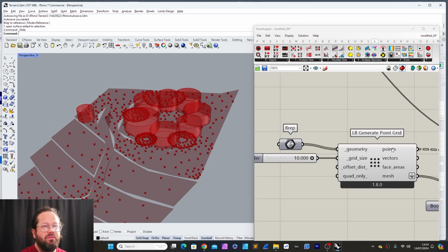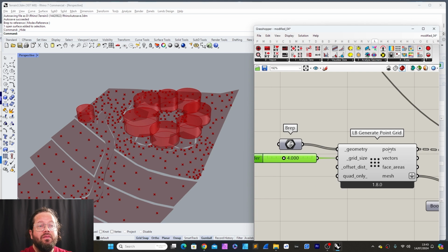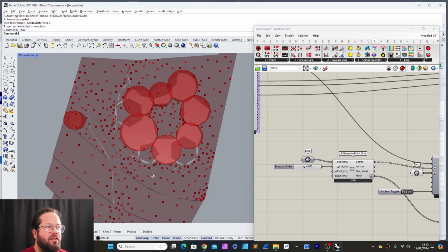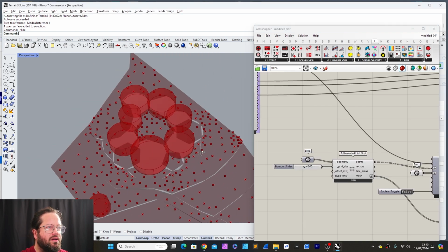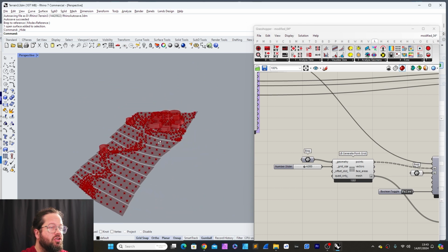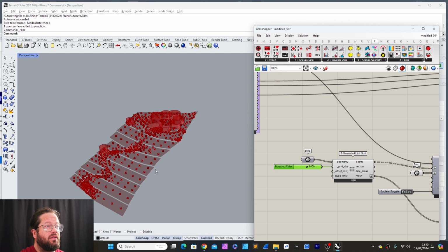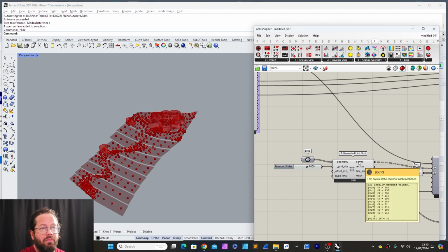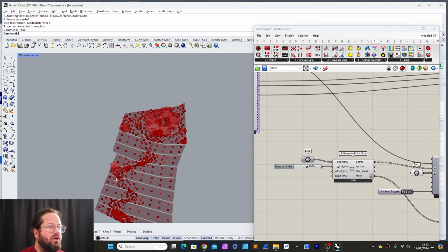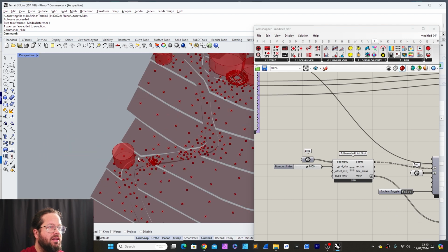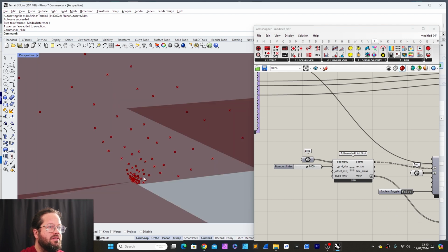We try to lower it, but we still have quite a lot of points, 1160 points. It's interesting because it feels like we had fewer points with the grid size 4. Very interesting. 896. I think it's something related to how the mesh or the surface is generated. For example, if I put 5 here, I actually see the distance become bigger, but I have more points. Something weird is going on. Maybe it has something to do with adding more points in here. Maybe that is the reason.